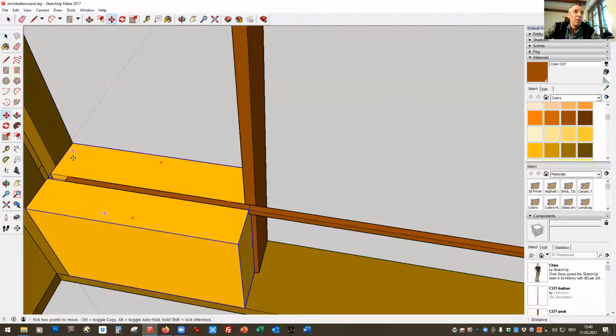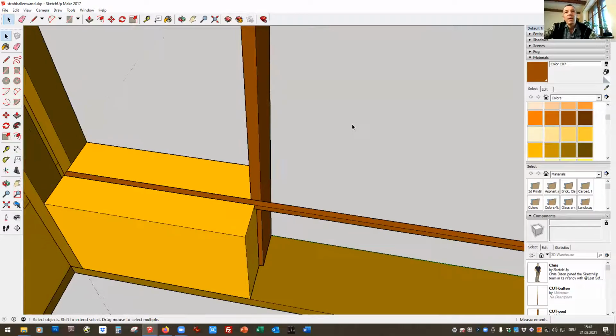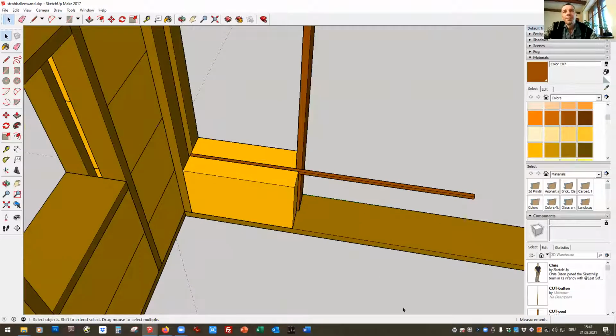So what we want is to move this bale, this batten, to the end, like that. So I have here the batten. I have a cut post. This is the main principle of a cut wall. This batten will fix the bale here so that it cannot jump out or jump in, whether I have a diagonal bracing or a board outside or not, or directly plaster it.